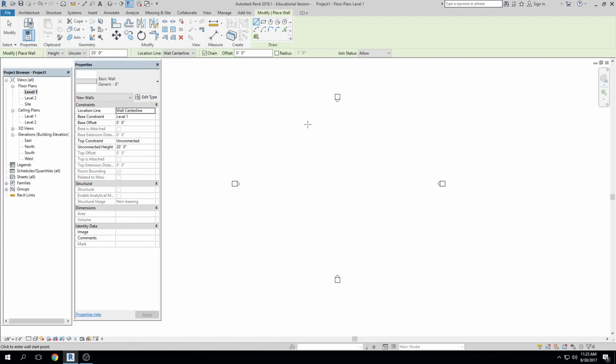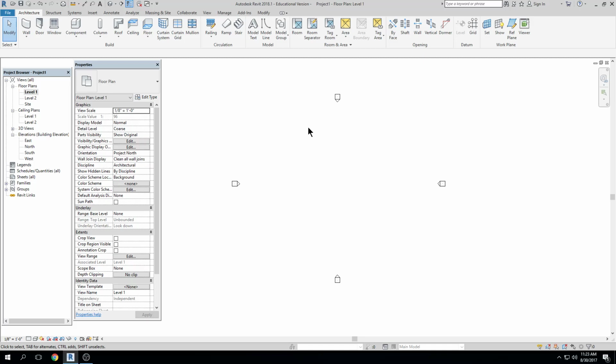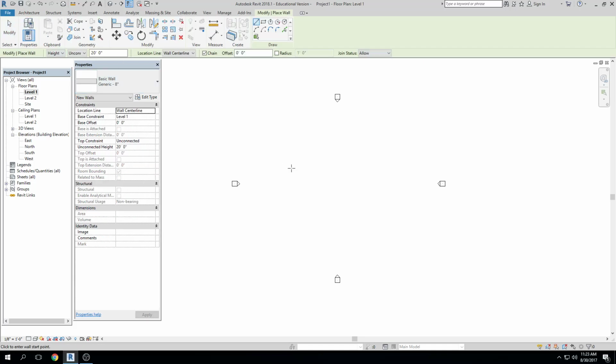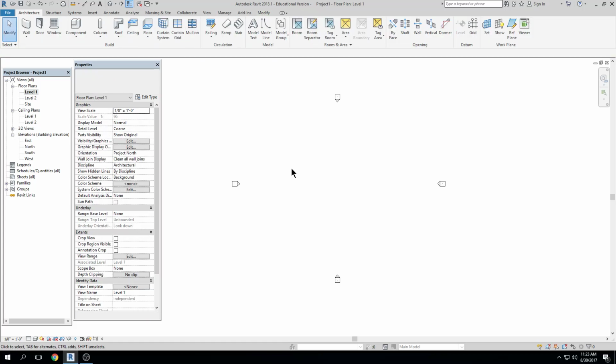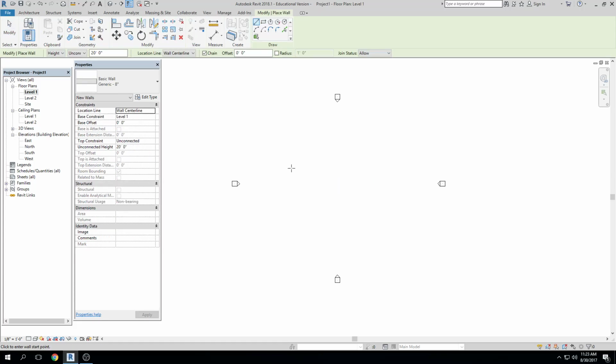So by doing that, if I hit escape, do you see how my cursor is an arrow, right? But if I click on wall, I can also type WA, right? For those of you that want a keyboard shortcut, escape, escape, WA, it initiates that same command. I'm going to get used to those shortcuts, I haven't yet though. So I do that and it initiates the command.